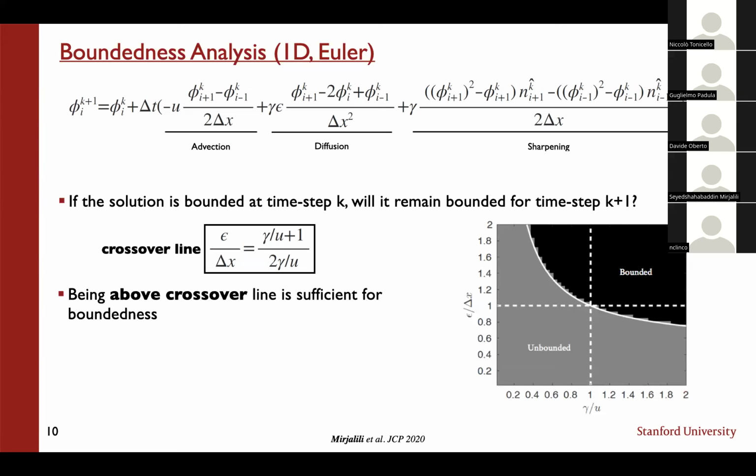It's similar. It's more like a cell-Peclet condition for scalars, right? You have to have enough resolution to capture them. Here, you have to have enough diffusion to be able to capture it. So it's kind of similar. The nice thing about it is that it doesn't enforce an additional constraint on the time step. Okay, sure. It's already there, yeah.